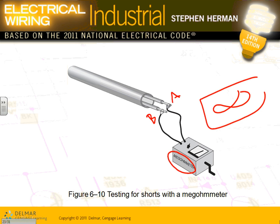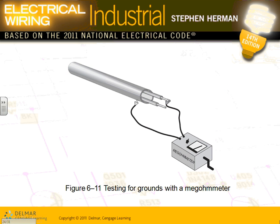It shows that these two conductors are not tied to each other. Again, from the load side, you disconnect them from the load. Then they take phase A and tie it to the conduit, and it should show infinity, meaning your phase A is not grounded. You do the same thing for phase B, the same thing for phase C.